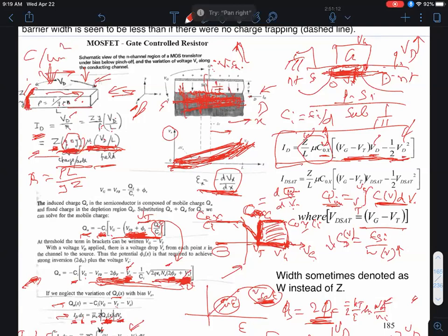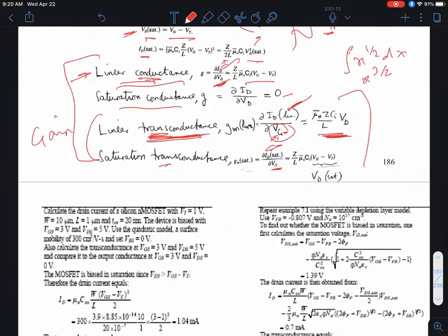Now, if that was the case, and because I have a thicker inversion region over here, it's as if the cross-section of the resistor is thicker near the source end, and thinner near the drain end, right? And if we have the same electric field, what's going to happen? I cannot satisfy current continuity, right? But I have to have the same current flowing across every cross-section. So as my effective thickness of the resistor shrinks, the electric field has to increase by exactly the same amount, so that the product stays the same throughout. Makes sense. And it's the same physics as for the JFET or the MOSFET that we mentioned a couple of lectures back. Very good question.